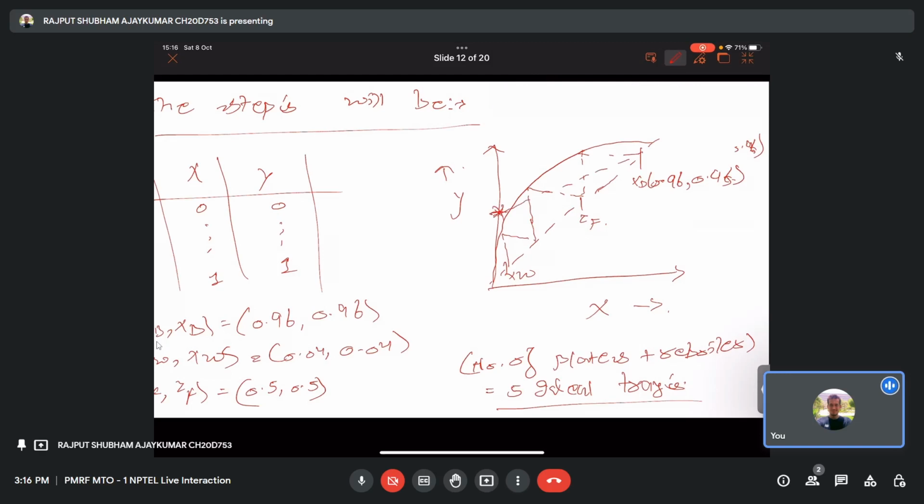So in each case, fit the ideal stages between the operating line and the equilibrium curve and determine the bottom concentration, that is xw. So what you have to do is to determine the different types of operating lines, fit the equilibrium and operating line, and find the bottom concentration, that is xw, using the data of xd and xw as well as the slopes of the bunch of operating lines. I have drawn one here. So this is one of the operating lines. In the plot, you can determine specifically the data.